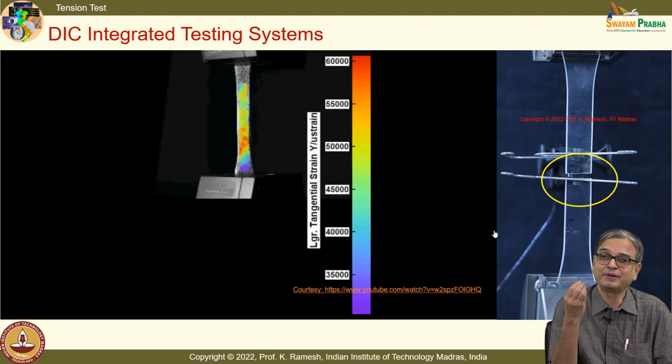So, a brittle material fails by maximum normal stress, that is a reasonable approximation, and then a ductile material fails by shear stress reaching a maximum, as we have discussed till now. We will see that further.